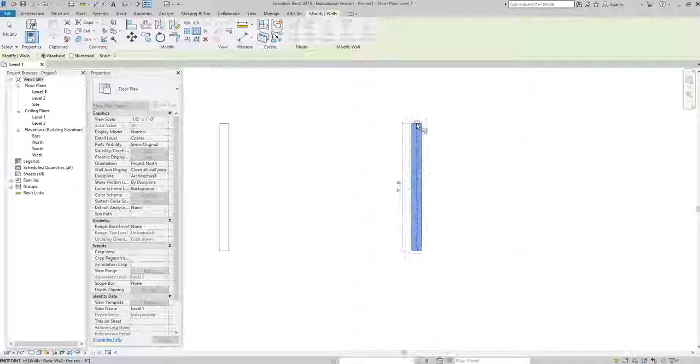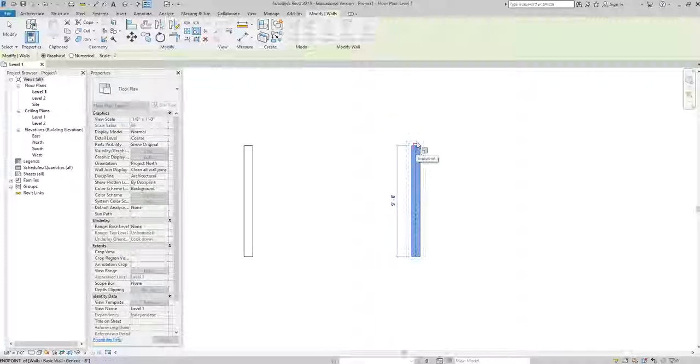Okay, now this command continues on. So instead of entering a scale factor right now, I'm going to enter the length that I want that object to become. So I first specify how long it is, and then I say, but I want it to be 12 feet long, right?